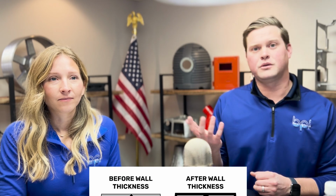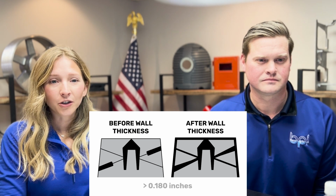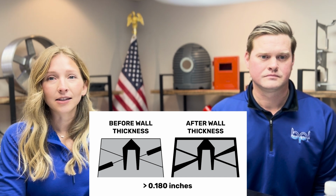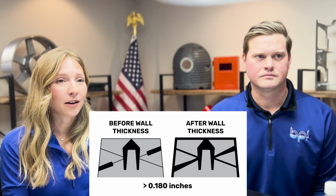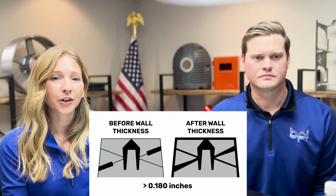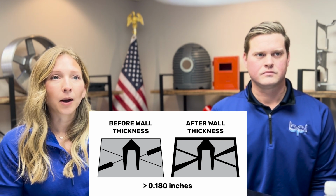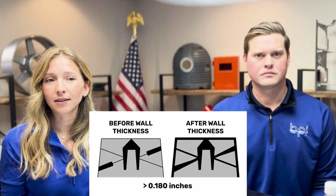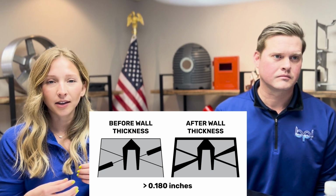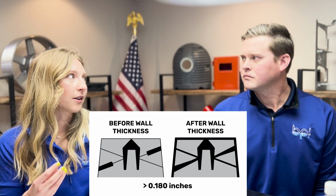Absolutely. So the first thing we'll talk about is wall thickness. Rachel? Yeah, sure. So in general, 180 thousandths is pretty standard for permanent mold. I would say that's your minimum in most cases, and when you're designing for permanent mold, or really almost any casting that is gravity fed, you want to consider consistent wall thickness for your casting, and then looking at maybe machining or polishing to get down to the exact wall thickness you want. Because if you have too much variance in your wall thickness, you'll see it freeze out in certain areas and you'll get non-fill. So it just makes it a little bit harder to cast if you require a lot of different wall thicknesses throughout the casting.